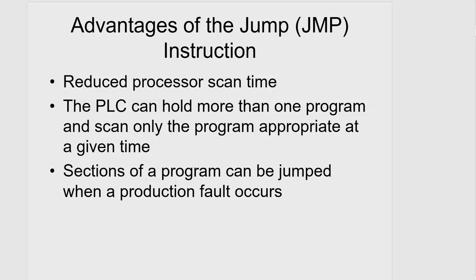The PLC can hold more than one program and scan only the program needed at a particular time, which can be an advantage. Imagine you have 4 programs on one long rung, and depending on the condition being met, you can jump to the first program or the second or the third or the fourth, again saving valuable scan time. Rather than scanning through one long program, you can divide it up and only go to the part or sub-program you need at that particular time.